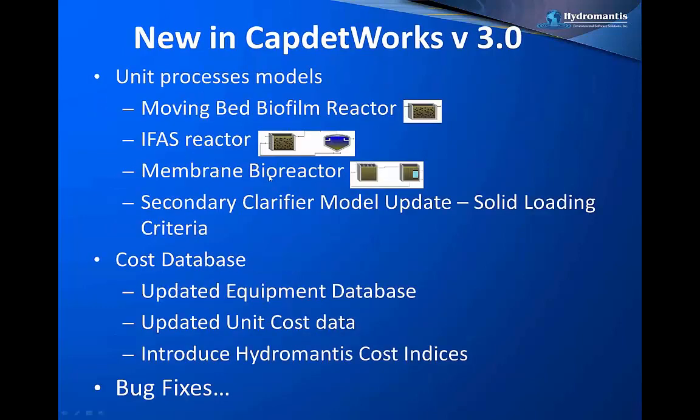In addition to that, we have added a number of unit processes in new CapdetWorks. One of the biggest requests we had in previous years is the inclusion of moving bed biofilm reactor, IFAS reactor, and membrane bioreactor. So we have included all of these three new processes in the new version of CapdetWorks.